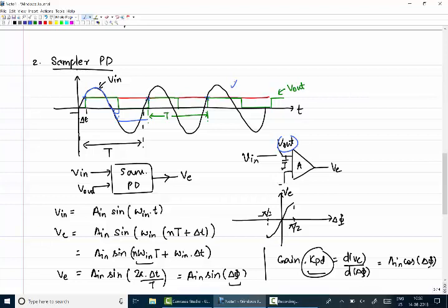Now, yeah, the sampling point is only delta t time shifted from the pi by 2 phase, right? Yeah, I'm sampling only at the rising edge of the clock. If I just have this V in and the switch and this capacitor, the actual waveform will do as I have told. It will come here, and when the switch is off, it will hold. Then again it is going to track. That's a track and hold, but I am trying to just sample it and take the value.